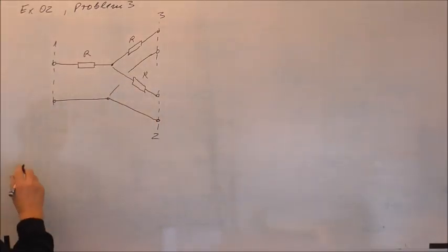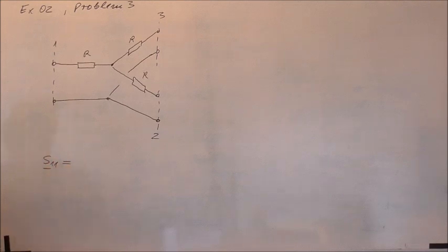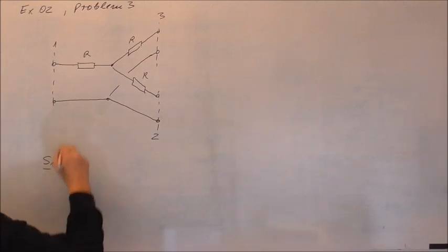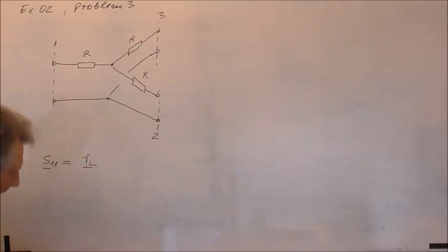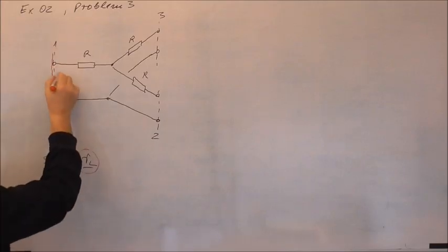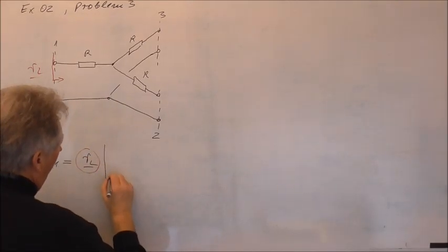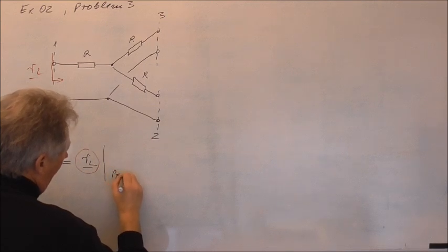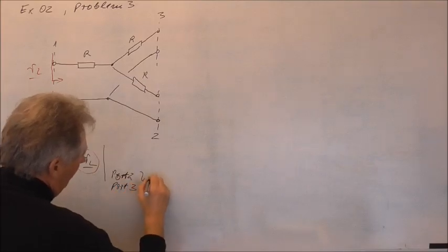And now we go to the point again and say S11 is 0. Of course, it's in principle the input reflection coefficient I see into this network here. We see here RL, the load reflection coefficient, if port 2 and port 3, they must be matched.